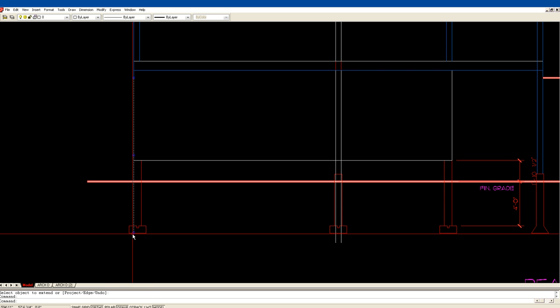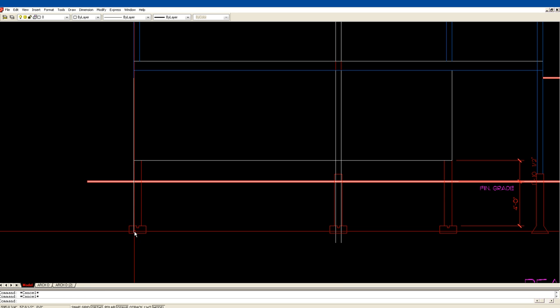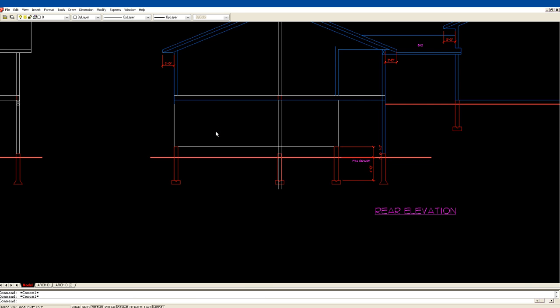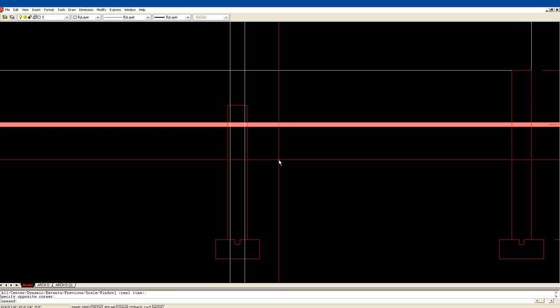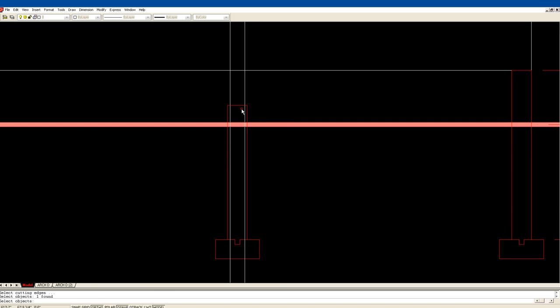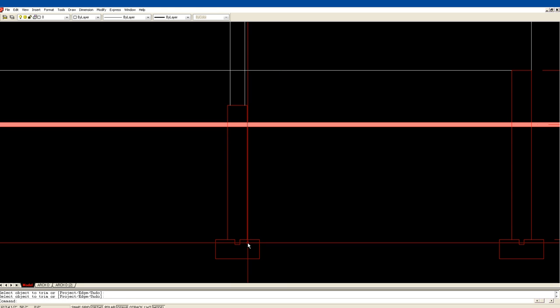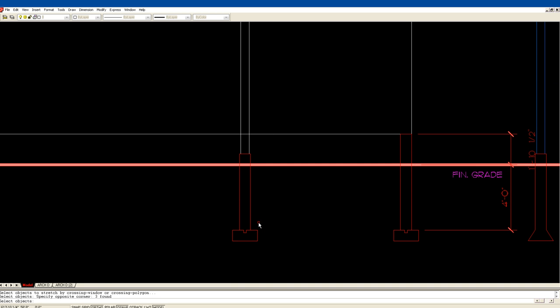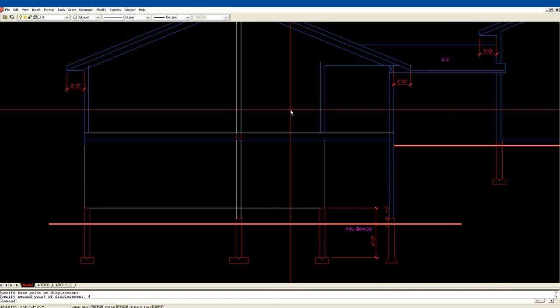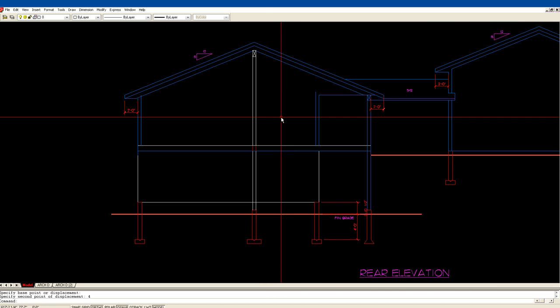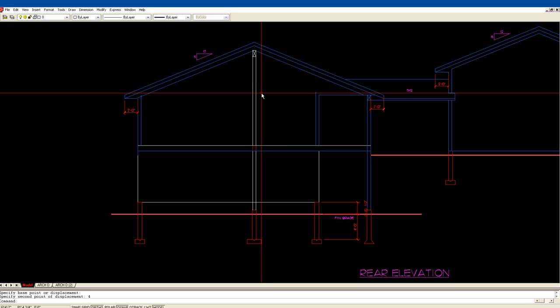This white line for the outside of my house. If I can click on it, we go back up to here. Okay. Something's wrong here. Oh no, it's good. Okay. So I've got 8 inches of concrete. Now here, I want quite a big footing, so I'm just going to stretch this out probably another 4 inches. And we'll do the structural calculations afterwards, have a better look at how we're building that. For now, it's just an elevation.